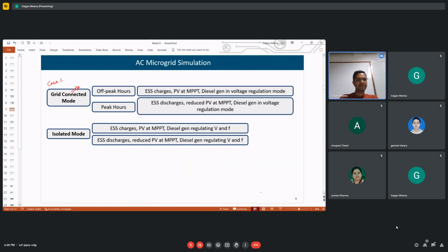What is the minimum voltage here? 0.9 to 1.1 pu. Yes. So the minimum voltage is 0.9 and the maximum 1.1, especially in the transmission system. Generally it may even be tighter than that, maybe 0.95 to 1.05.